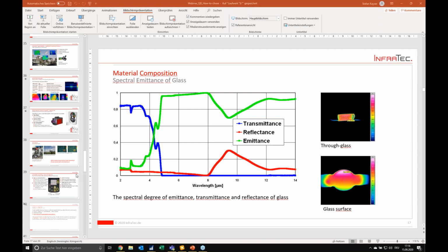One approach is to reduce the frame rate and then only look at the resulting image. One approach is to have some kind of a rolling image acquisition. That means each time you only update a quarter of all the pixels in an image, so you keep displaying all of these sub images in the larger matrix.